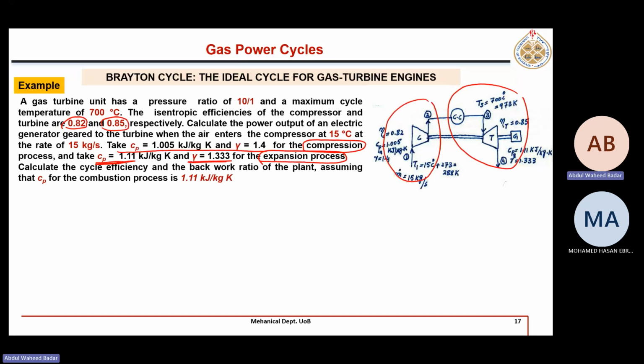It should not be 10 to 15% higher. It must be in this range. For a newly built turbine, if you do an experiment, and if you compare it with the ideal one, there will be a difference of 10 to 15%. Right? If you are using proper bearing with as little friction as possible, it should be in 10 to 15%. That's how we know from experimentation.